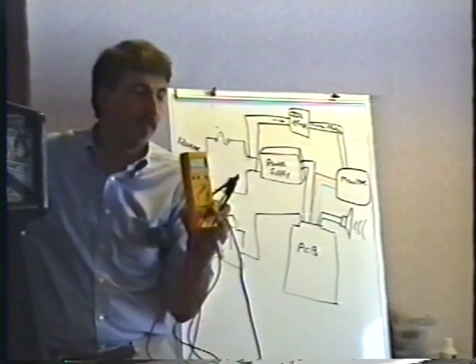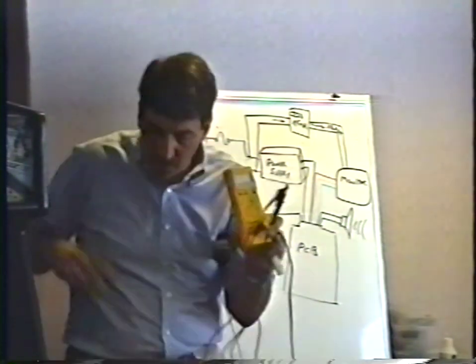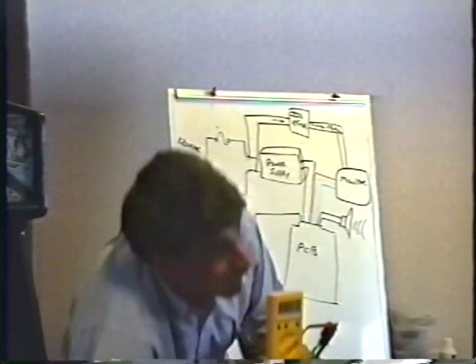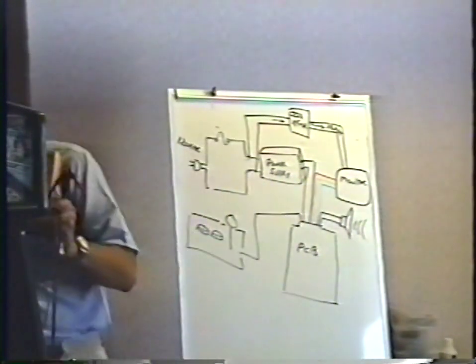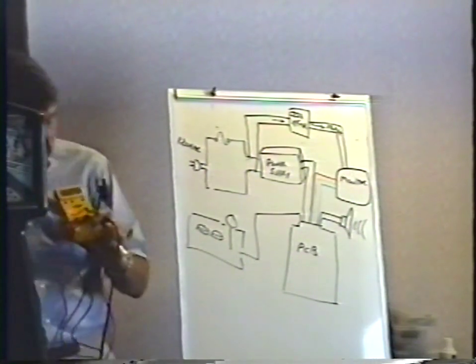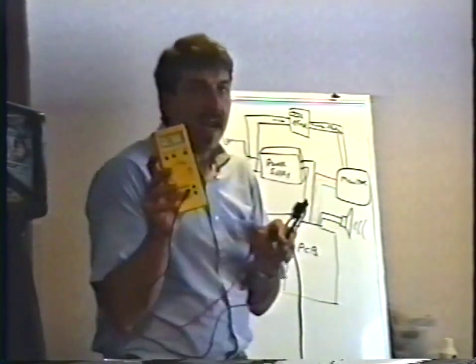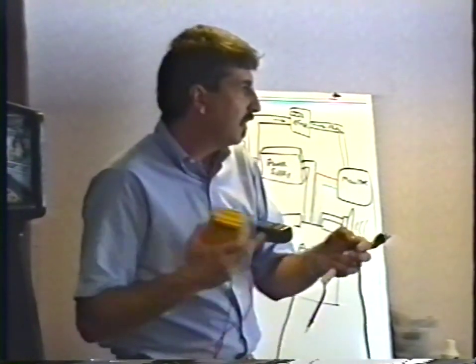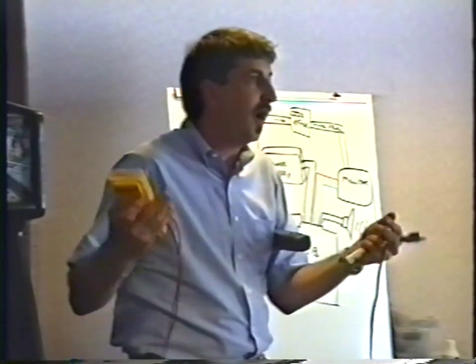Make sure all the switches are on. Are they on or off? There's an interlock switch in the front door here. Is that pulled out to turn it on? There's one in the back door. Are all the switches on? Yeah, they sure are, but I don't have any reading on this meter whatsoever, so I've got a broken wire somewhere. Something's broken, blown fuse, broken wire, something.